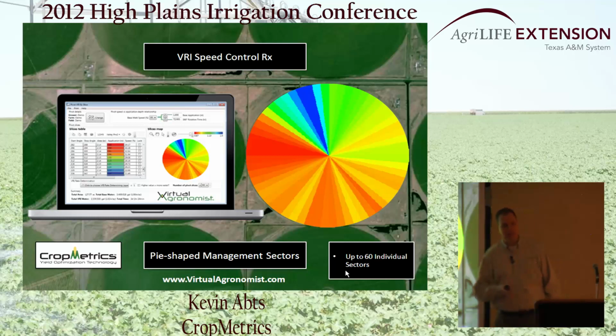This is what we call a 60-sector VRI speed control prescription. Prescription's what gets loaded out to the sprinkler controller that allows us, in this particular case, to manage the speed or application depth of water every 6 degrees within this 2-acre sector. Again, the advantage of this type of technology, this type of control, it's very simple to do, highly reliable, and I'll talk a little bit about what type of controllers allow us to do this.